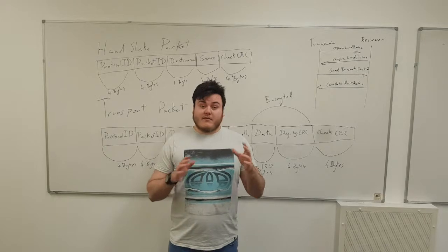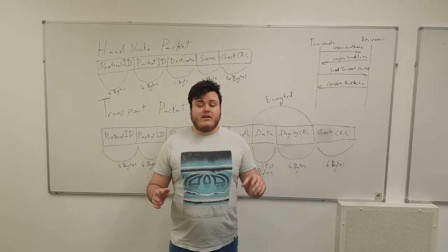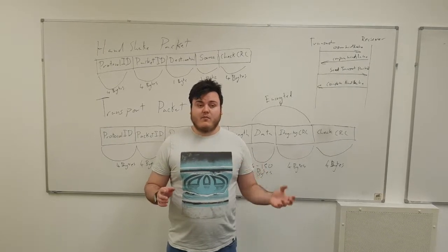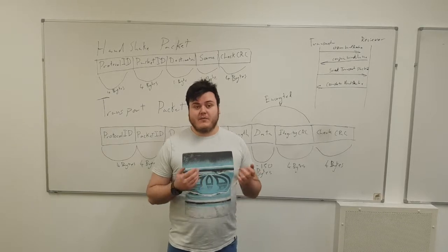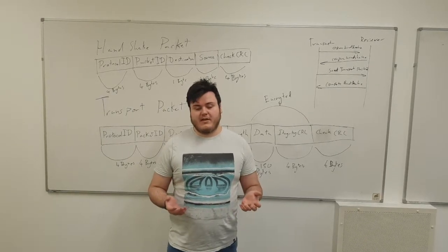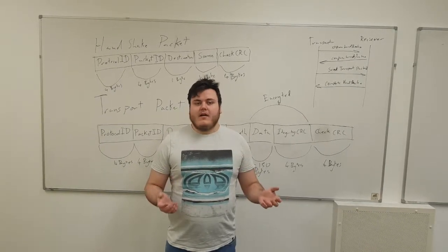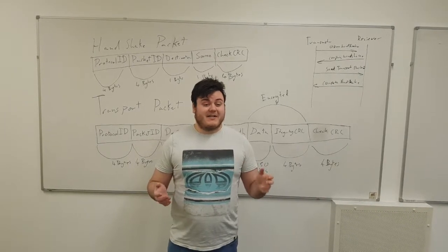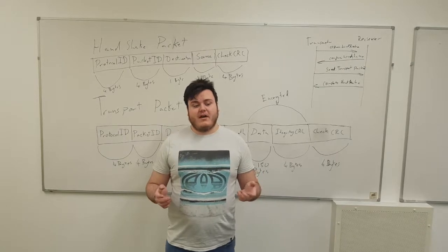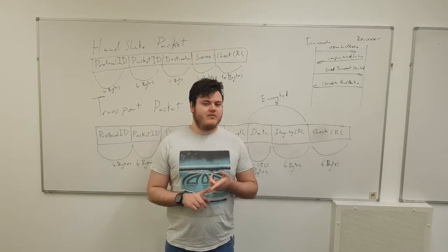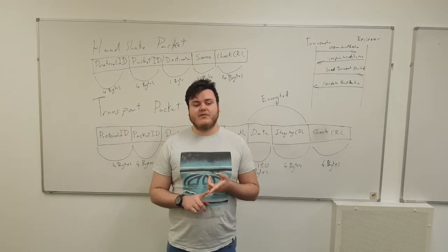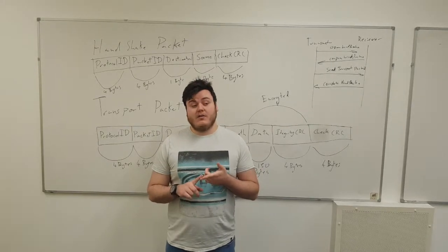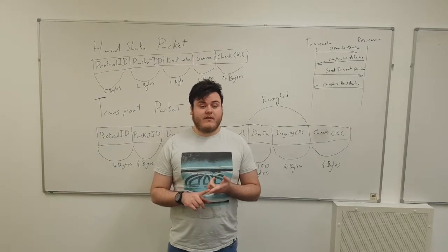At first this seemed to work fine. Unfortunately, the problem was that the transceiver we were supplied could only handle up to 180 bytes at a time, which meant that any of the main established protocols that we use across IP would be vastly too big.